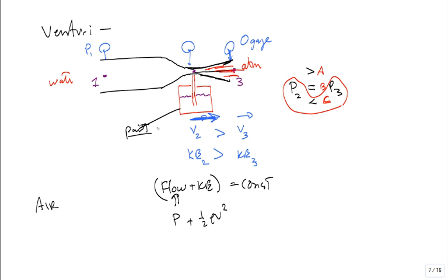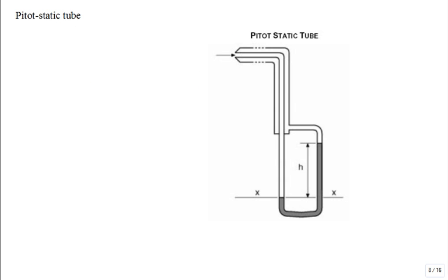You could have a little tube going down the liquid paint, and then that's drawn up, and so it's an air paint sprayer, and it runs off compressed air in the back, right? So you'll see that often, and it's explained with Bernoulli's equation, and you see why the pressure in that throat's much lower, and it can draw up other fluids. Let's talk about a pitot tube.